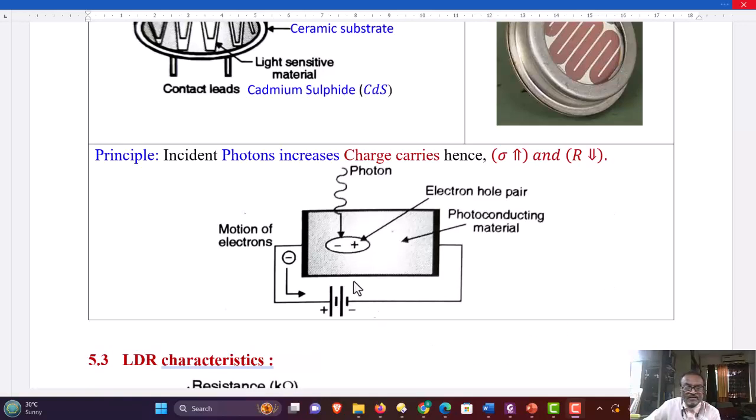visually. See, when the conducting bar is excited with the external potential, initially the resistance of this material bar is large. When photons are incident on the material bar, they will break the covalent bonds and generate the electron hole pairs. Those are available for the conduction, and therefore the resistivity of the bar is decreased, which is proportional to the incident photonic energy.